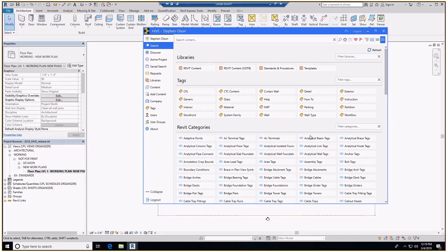So, types of content that lives in here. All Revit families live in here. What's called system families live in here. So previously, if we wanted to give our team access to, say, a library of different wall types, we would have to save those out into a remote location, or we would have to have an exhaustive list of wall types loaded into our templates. Same with ceilings or floors and that type of content.